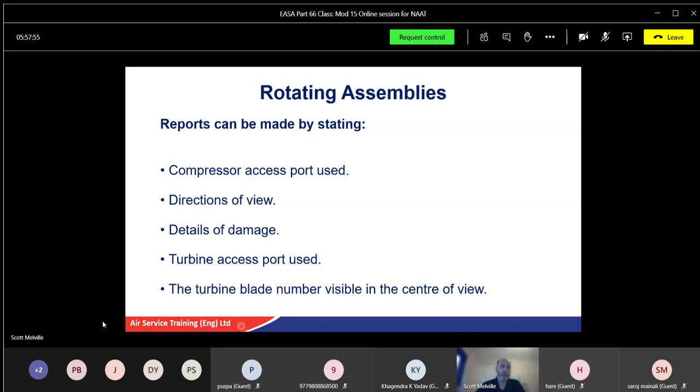And then normally with these borescopes, you can take a picture, upload it to the computer, and send it to the manufacturer for confirmation. If it's not quite within limits or it's just outside limits, they might give you a concession to say, okay, we'll give you 10% extra lifespan on that because the engine's due to come out very shortly. Or they'll say, no, it's definitely out of limits. So if you're unsure, get a second opinion, get in touch with a representative, and they'll come and double check it before they actually take the engine out, if it's that bad.